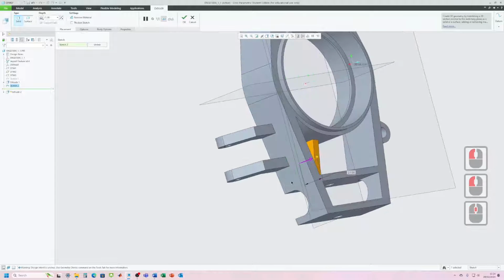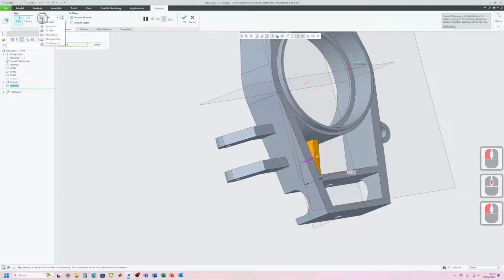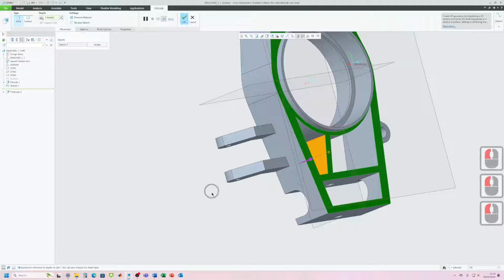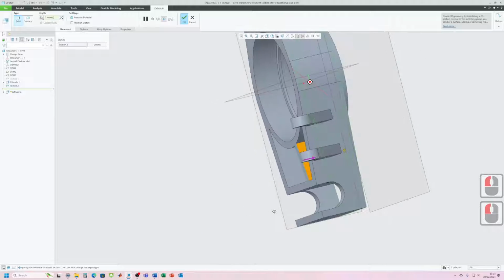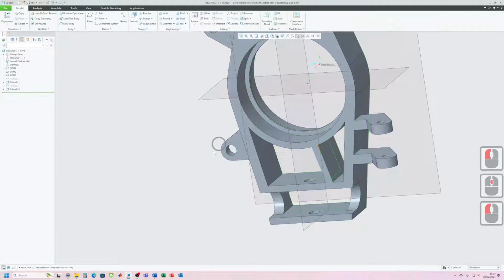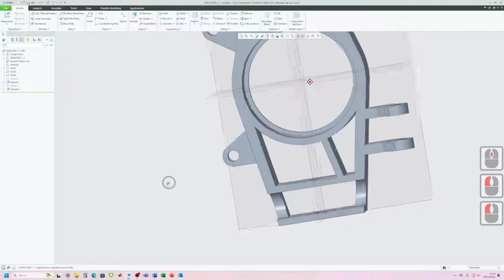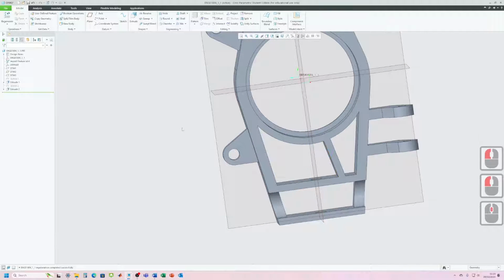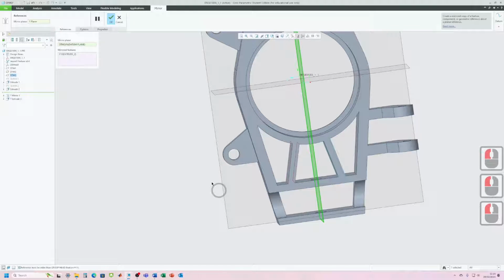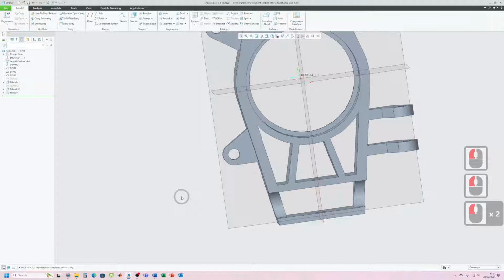and I'm going to use this tool here. So if I go to reference on this drop down, I can make it so that it extrudes through to that face, and we can click OK. So now I've got one bit of strengthening just there. Let's add another. Let's just mirror that. So if I click on that extrusion, click mirror, click the mid plane, I can add a second one in there. Okay.